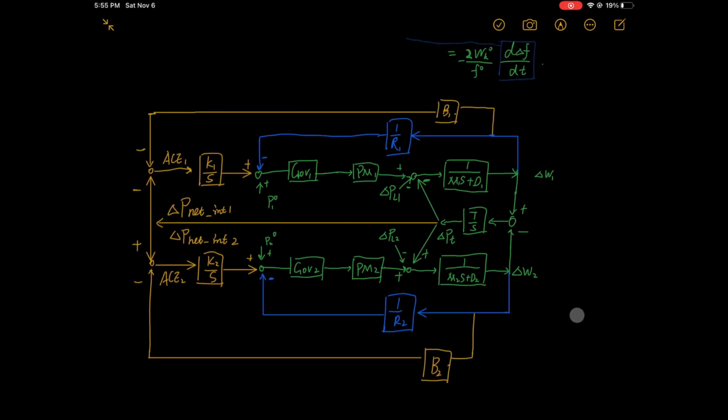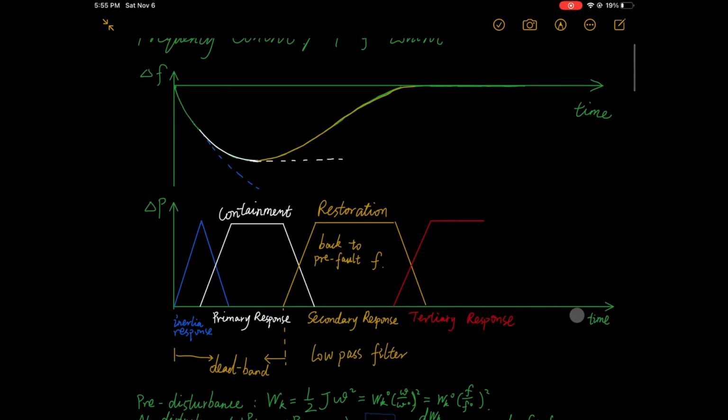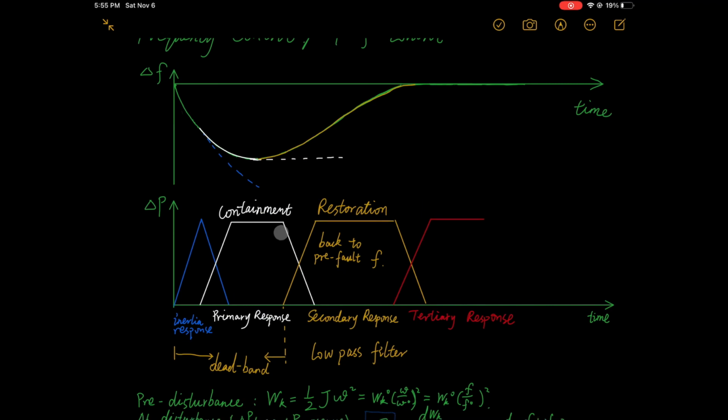A short summary for primary and secondary frequency control. Primary frequency control is imposed once turbine speed deviation is detected. No communication is required and economics is not considered. Secondary control, or automatic generation control, is triggered by a central signal and can bring frequency back to its set point value and bring tie-line flows of connected systems to pre-disturbance values.